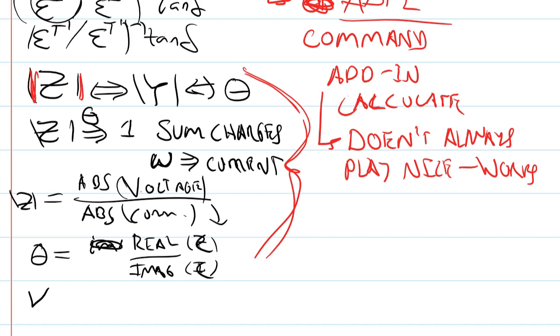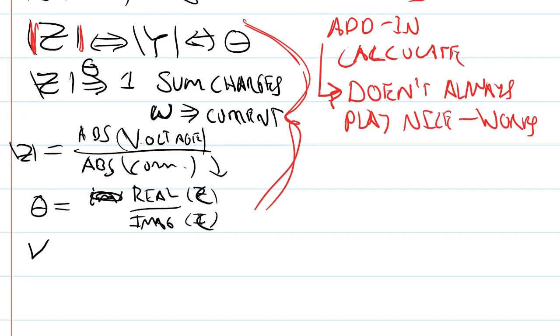In order to do calculations, it's not very convenient, and to come up with different ways of manipulating your parameters. Comsol really has a nice integrated way of doing that property manipulation if you want to come up with any different type of quantity, but Ansys does not. So you're gonna have to do some coding. So you can get these plots within Ansys.